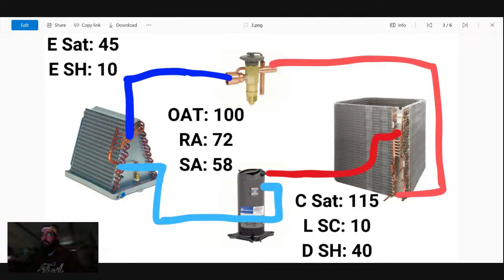If they're uncomfortable, is the system dehumidifying? That's a good question. Is it dehumidifying? What is the discomfort? They've got 72 return air. Again, that's a good question. At 72 degrees in the space, why would that be uncomfortable, or why would they be having issues? That is a good question.